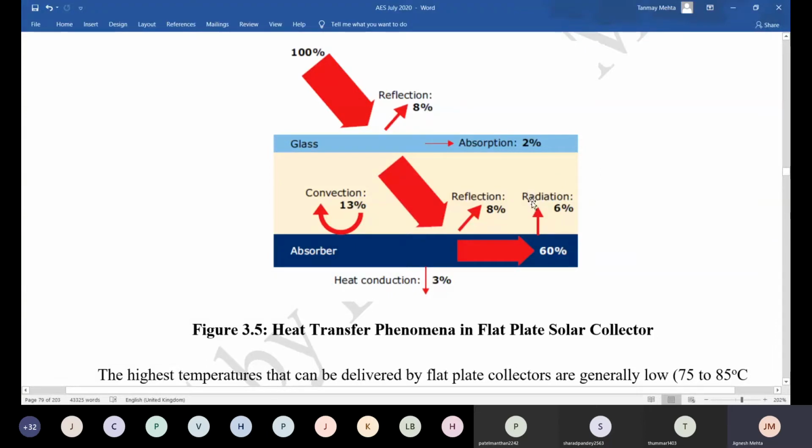Okay. Higher the temperature, generally overall losses increase, as well as the contribution of radiation increases. As you know, radiative losses are proportional to the temperature raised to the power 4 and the difference between the two temperatures. So it can increase rapidly beyond a certain temperature, right? So radiation loss is comparatively low here because it's not a very high temperature application perhaps. So the radiation losses are less. Okay.